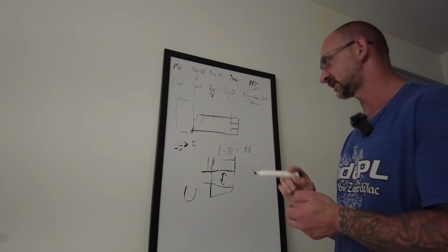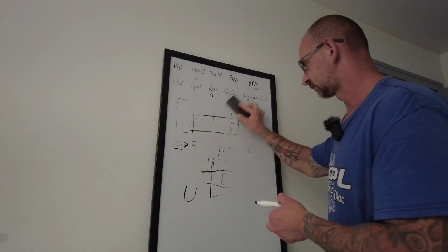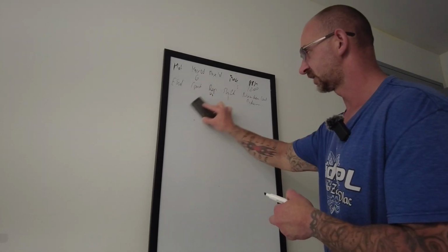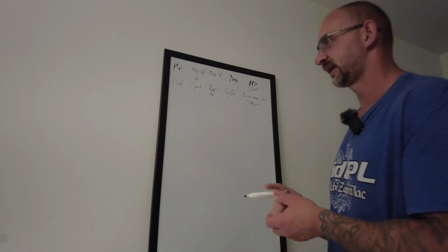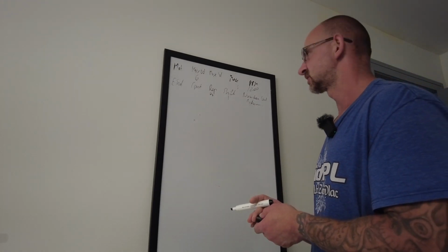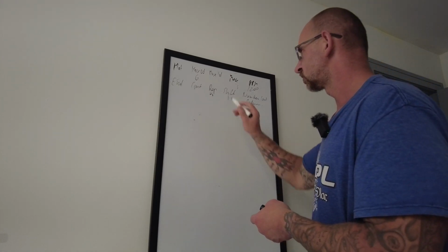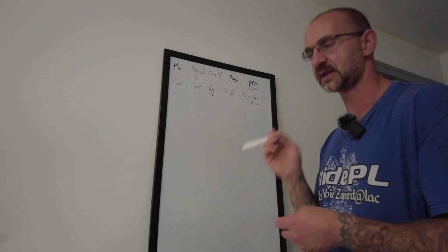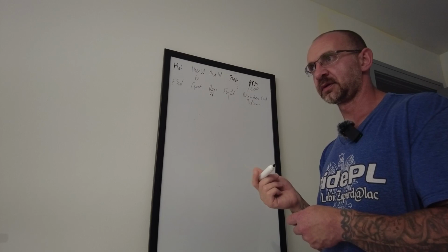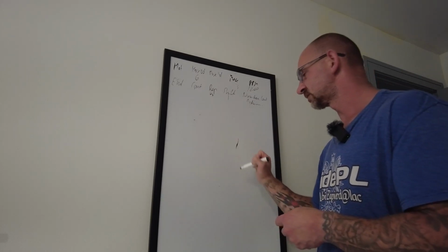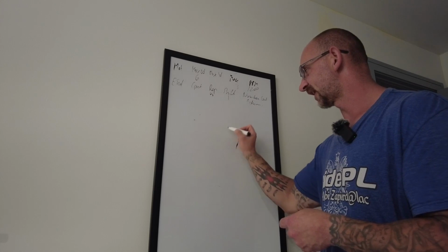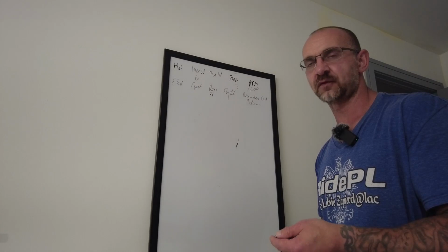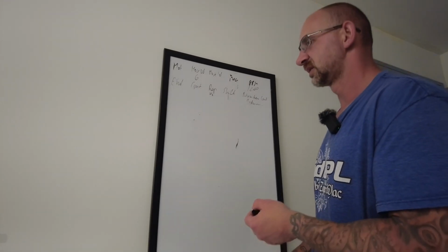Now this is very important, and I had this happen to me like 2 years ago. I couldn't figure out for the life of me what was going on. I actually had to call Mazak, and one of the application engineers figured out what happened. When you set this up, there's also a maximum length of the part. How long is your part? My part was 1 inch. I was doing five parts, so it's 5 total. But since the part is 1 inch, I just put 4 inches. This was my mistake.